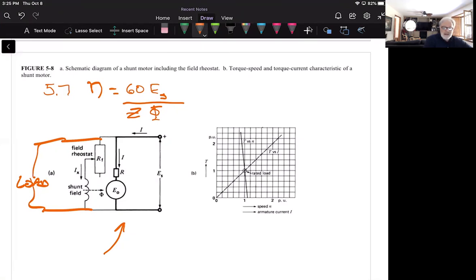Then once we get this higher torque, the armature accelerates again, and it will continue to accelerate until the torque developed by the motor is almost exactly equal to that of the mechanical load. Then at that point, the speed will level off, okay? And then, to sum up, as the load increases, the current rises and the speed drops, okay? And so in response to this, the torque increases, the speed increases until it matches, and so forth. And that's how this motor reacts.